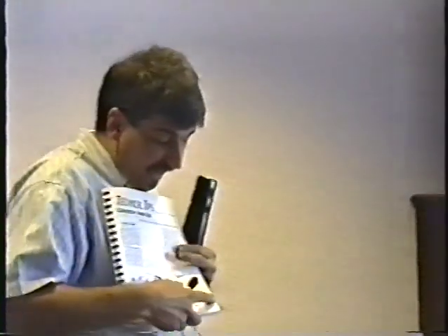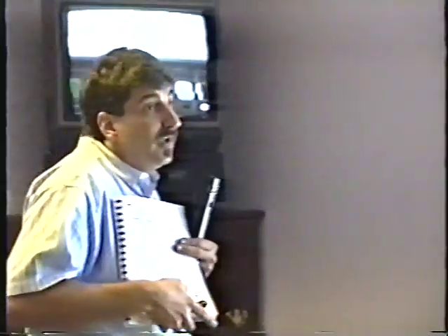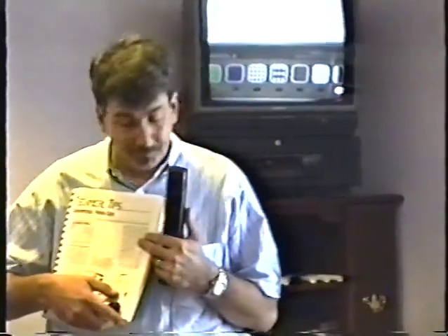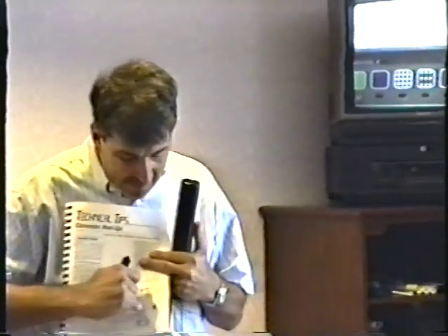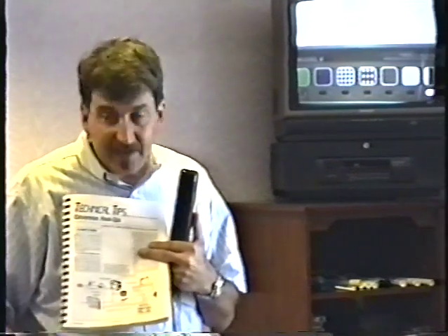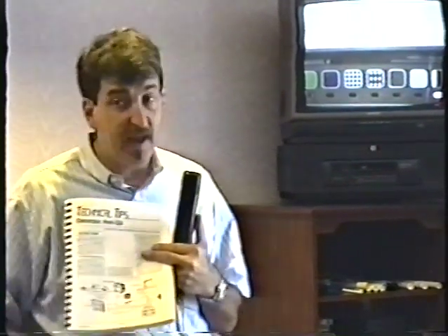I always use pin 4, and the reason I do that is after all, it's the video connector, and it's called video ground, and so I put it there. But you don't have to. As you saw on the connector of this pattern generator, it is on pin 4. And then the vertical and horizontal negative syncs go into pins 2 and 3 respectively.